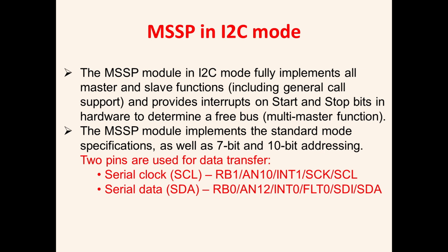So 128 slave devices you can connect to one master if your address is 7-bit, and if 10-bit addresses are there, then the maximum limit of slaves connected to your master is 1024. Clear?